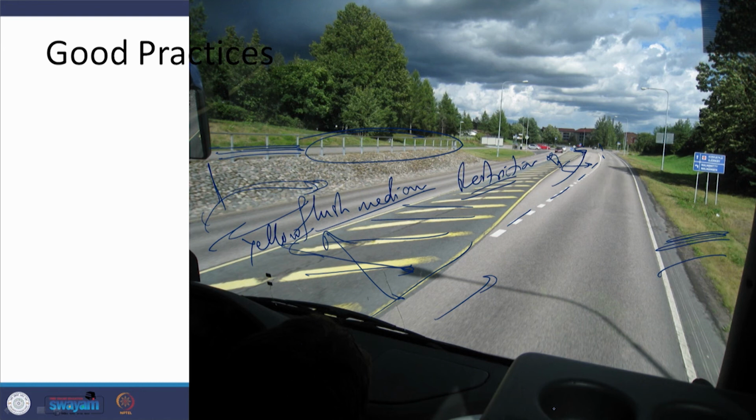So, that means the width of flush median or whatever type of median which has been provided should be sufficient so that it can come up with this type of a lane which is 3.5 meters wide. At the same time, the median which has a minimum width of say 1.5 meters. So, that means this is minimum 5 meters, if it is, then it has been helpful.